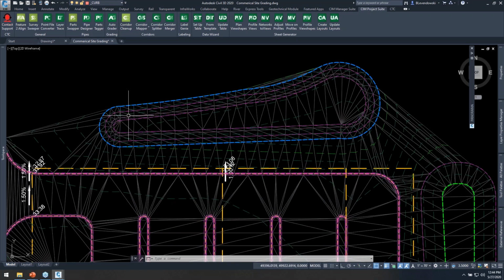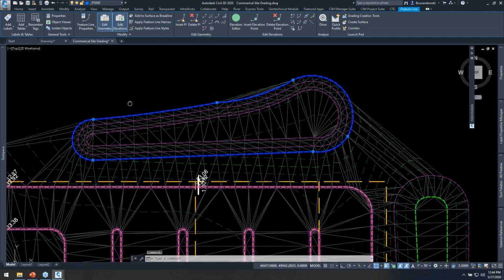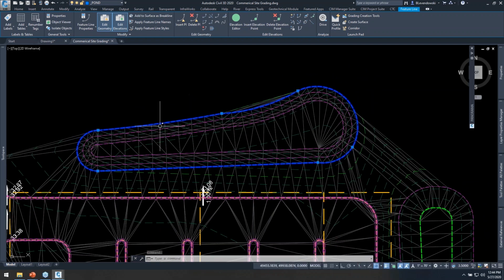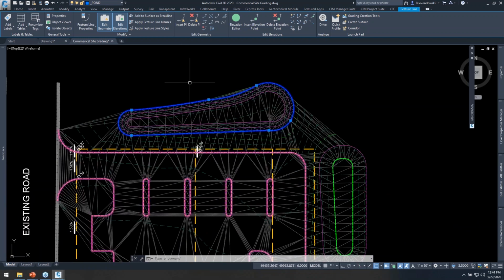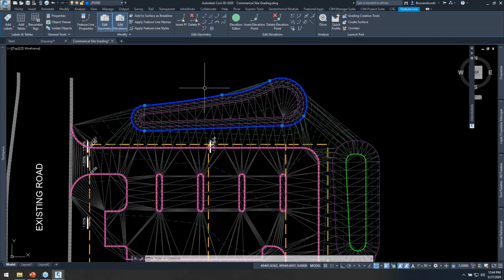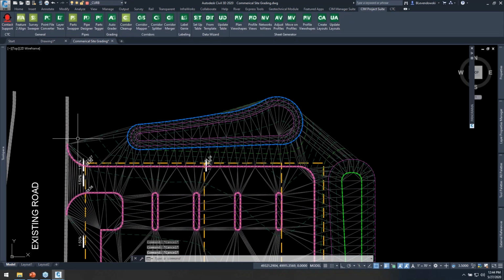And you can do it any way you want, okay? I could take this parent and I could daylight from this for a certain station range out like this. Or maybe you want a little more space and I want to define a buffer out here. And then I could just daylight from that parent feature line. Whatever you do, you can daylight from any feature line to any surface.